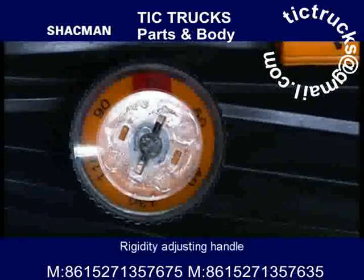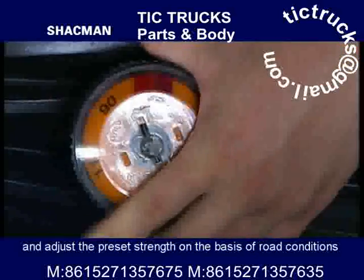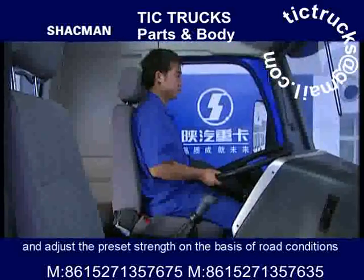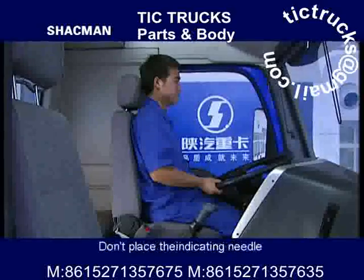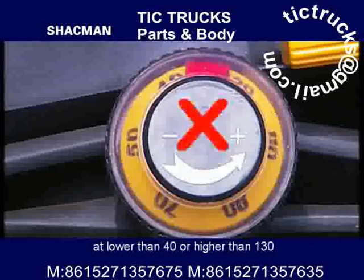Rigidity adjusting handle. Turn the seating surface rigidity adjusting handle wheel and adjust the preset strength on the basis of road conditions and the driver's weight. Don't place the indicating needle lower than 40 or higher than 130.